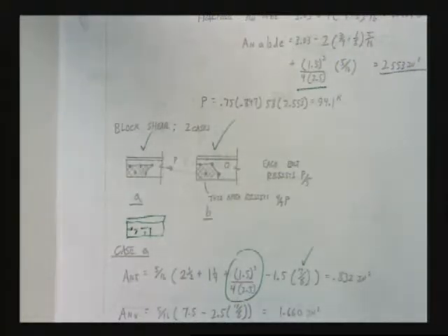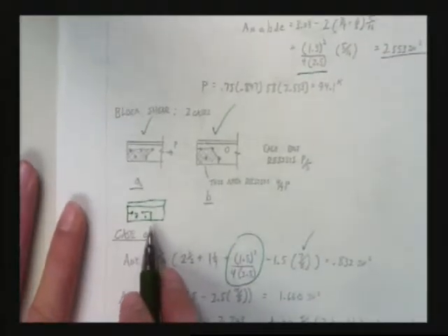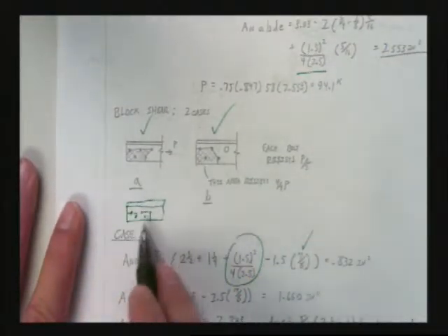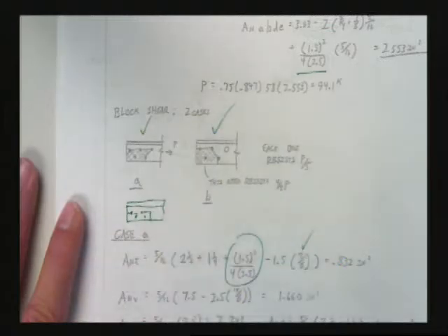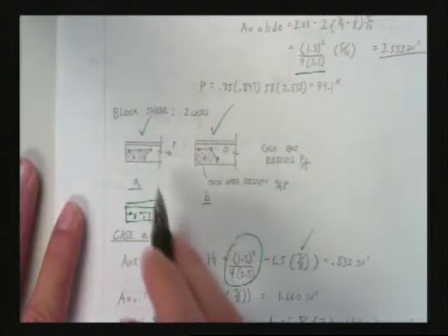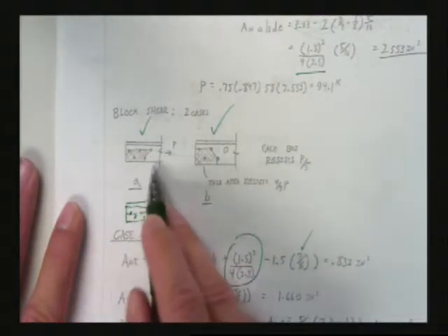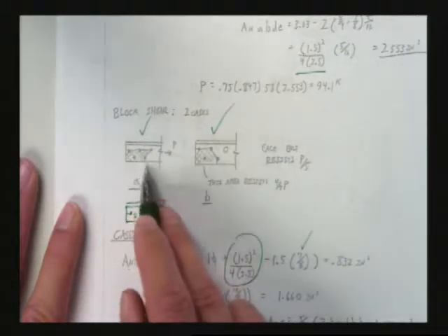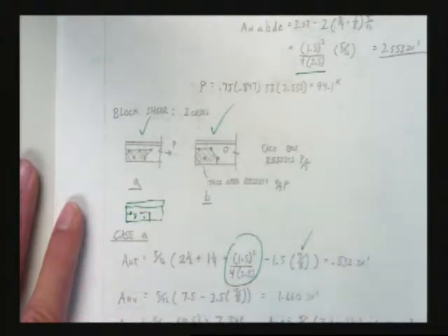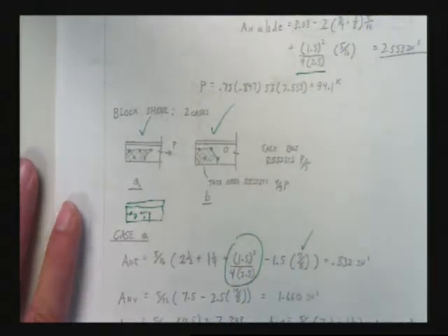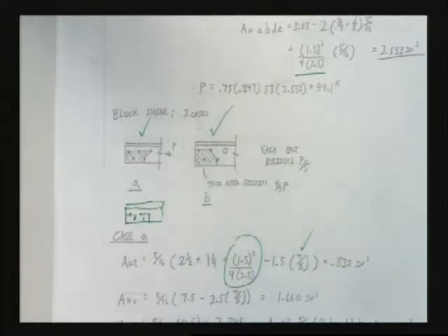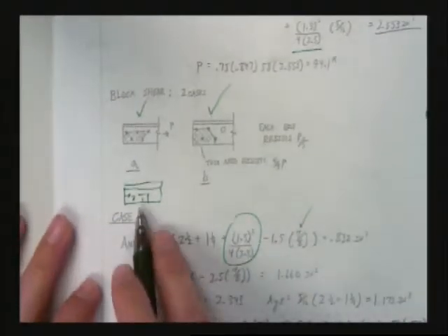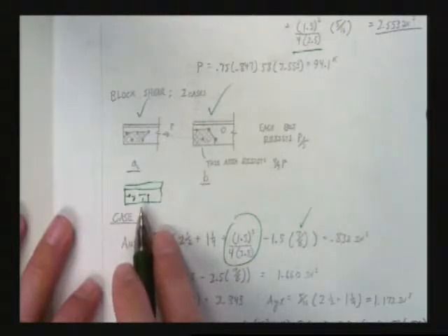What you're checking, what you're comparing here, is there more area involved to go straight across, or is there less area, however you want to look at it, or is there less area involved to go straight across through no bolts or half a bolt, or to go at a diagonal and go through 1.5 bolts? So the math is doing it, right? It's comparing that for you, putting them on a scale and deciding which one's going to happen. Okay? Should check it.